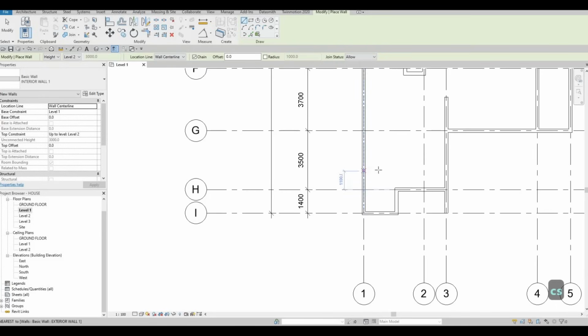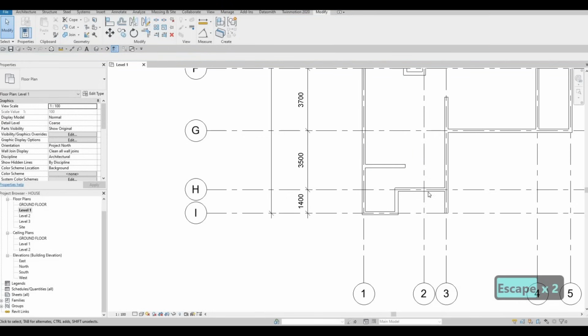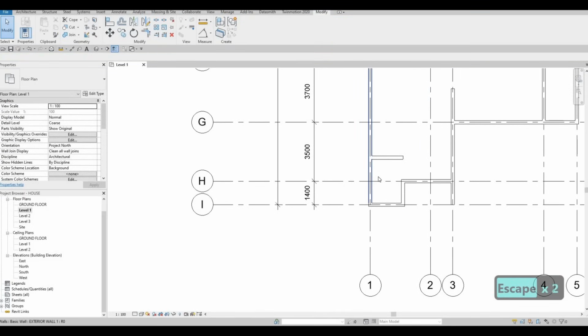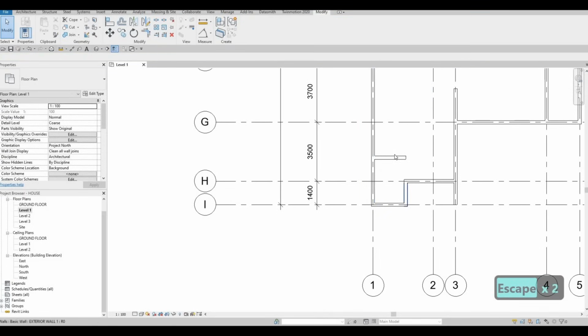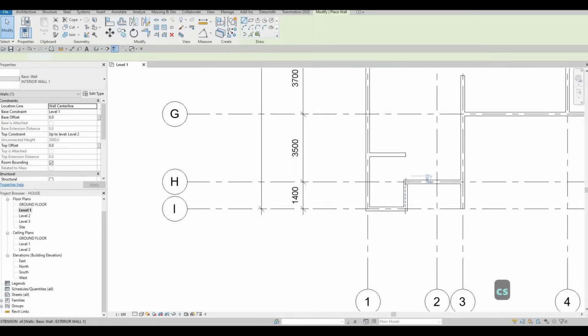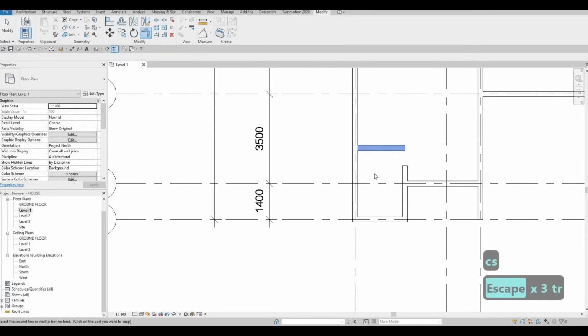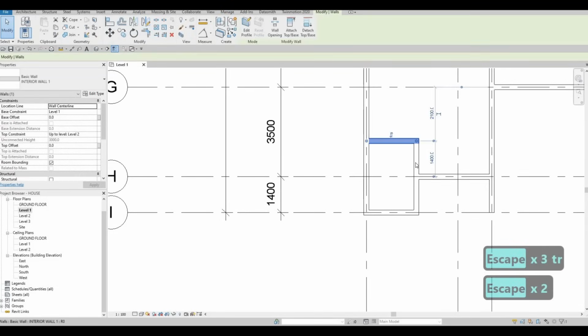So now, once everything is added, we could add in again a powder room here and a small closet. So what we could do is just have something like this. Once they enter, I want a double or a French door right here. We could just click this one right there, close it off. So TR, trim and extend, let's close off.